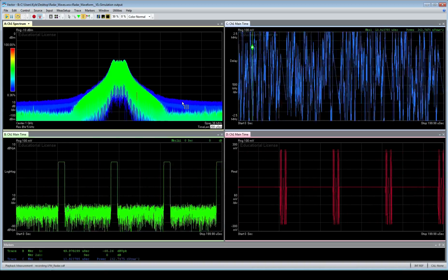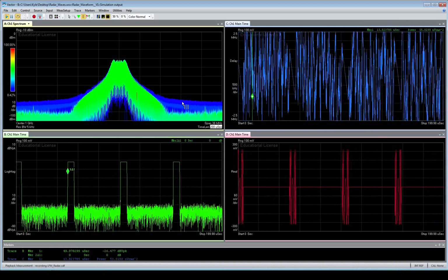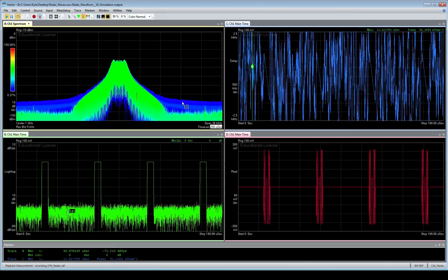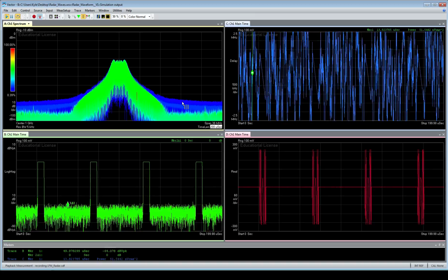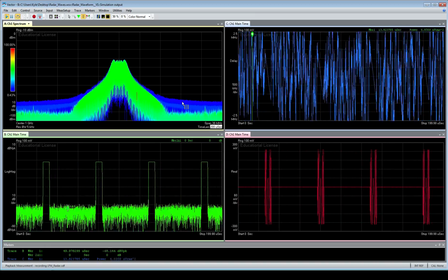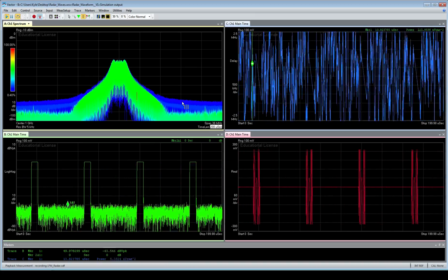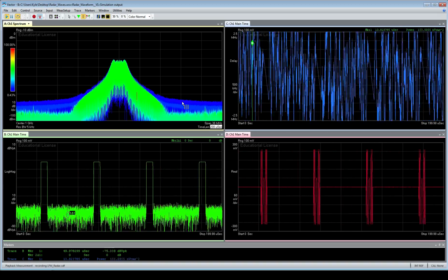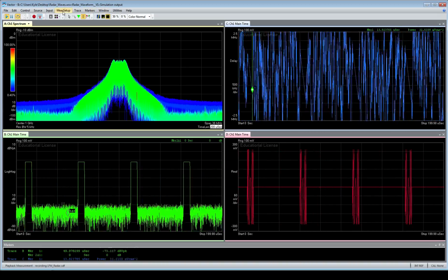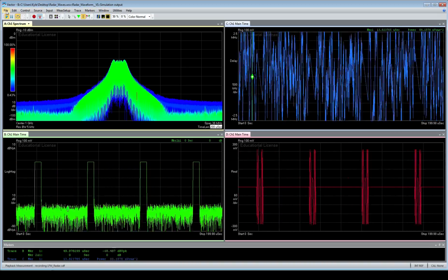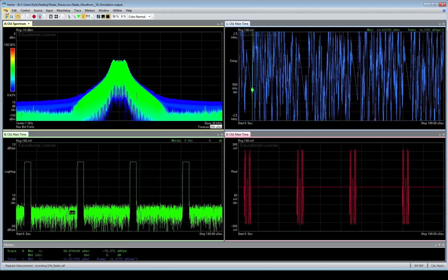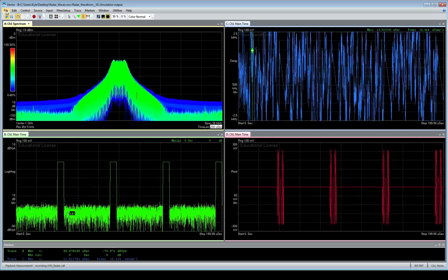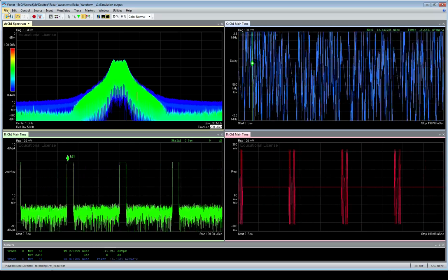The first one's a linear frequency modulated pulse radar. The next one's some linear frequency modulation with some jittering of the pulse repetition frequency, and actually some changes in the pulses themselves. A Barker code, and finally an FSK radar. So, for your background information, I generated all these radar waves myself from a variety of sources, some were in MATLAB and some use System View.